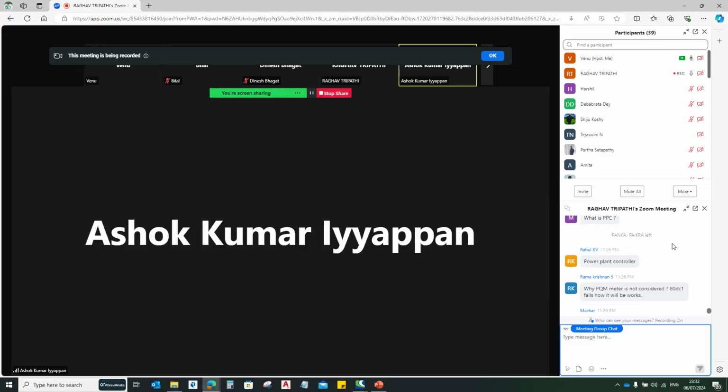Similarly, the DNO network has to share some information. For example, when the substation protection in the DNO network is operated, and the voltage values being generated at the generating station, these values should be shared with the national grid. That will be clearly listed in the connection agreement.